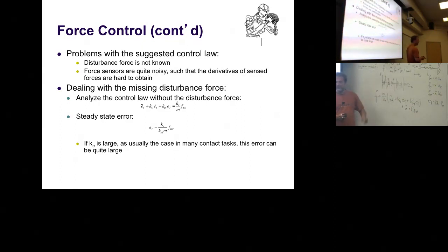If you take the derivative of this thing, you get an even bigger mess, so a numerical derivative. If you take that and filter it on top, then you get delays. And in force control, delays are even worse than what I showed you with delays or discrete time systems before in linear control systems. If you try force control with delays, you explode really, really fast.